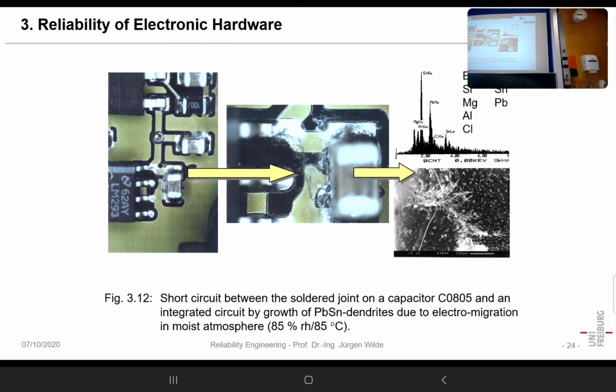For instance, you have salt, and in former times, salt always became cloggy, because it took up humidity. So you put in a grain of rice, for instance, dry. So that means when you have such hygroscopic materials, then you can have precipitation and formation of the water film below 100% of humidity.